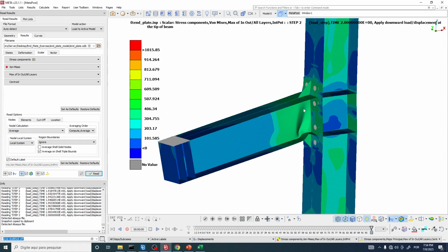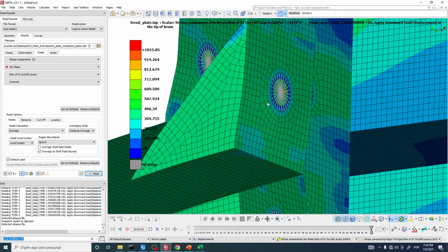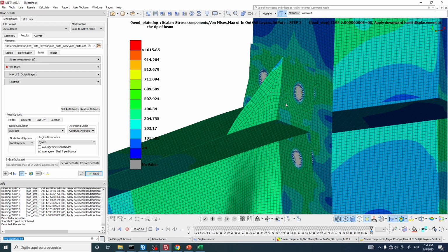We are also going to start the creation of the second model. Actually, we are going to modify this one. We are going to create the solid bolts and solid washer and nut, define contact, etc. So we're going to modify the model in the next video and also finish this post-processing.